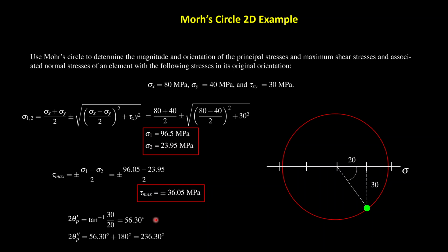Now we know that we have two principal stresses and they are 180 degrees apart from each other. So by knowing the first direction, I can know the second direction right away just by adding 180 degrees in Mohr's circle angles. I'm repeating Mohr's circle angle because the angles represented in the Mohr circle are double what is represented in reality, and we will see that.